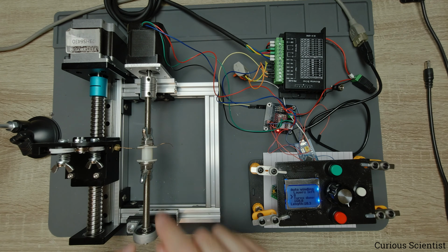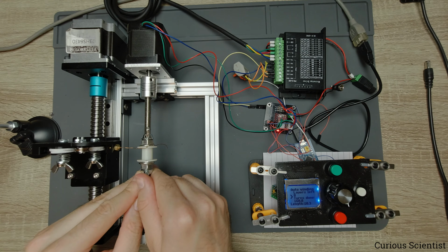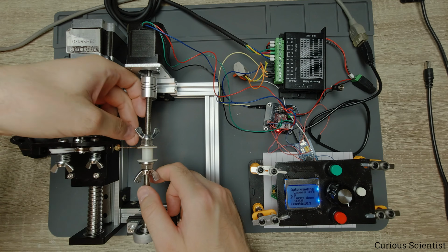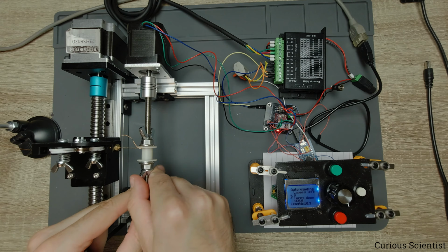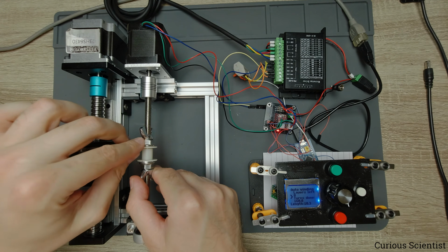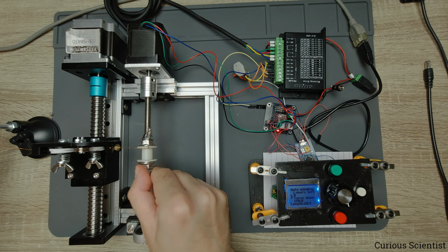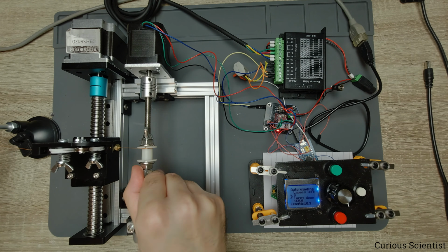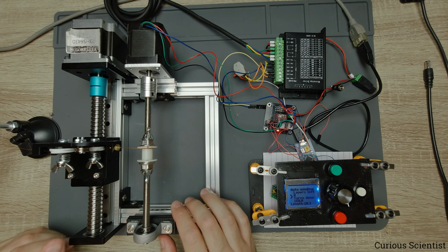So I more or less put in the wire, and now what I have to do, I have to prepare 2 turns. I wrote the software in a way that we already expect the user to manually prepare 2 turns, and the reason behind that is because the 2 initial turns have to be packed nicely in the bobbin, so therefore that has to be prepared by the user, and that's what I'm doing now. So 1 turn is done, and now I'm doing 1 more turn to return. So now there are like 2 full turns on the motor.